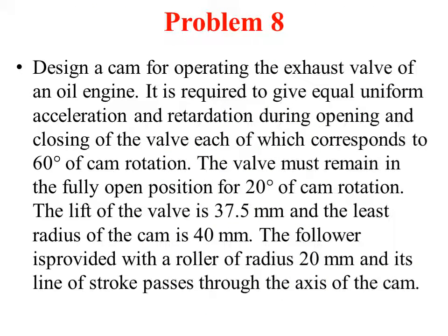Moving on to the next problem, they are given: design a cam for operating the exhaust valve of an oil engine. It is required to give equal uniform acceleration and retardation during opening and closing of the valve, each of which corresponds to 60 degree of cam rotation. The valve must remain in fully open position for 20 degree of cam rotation.